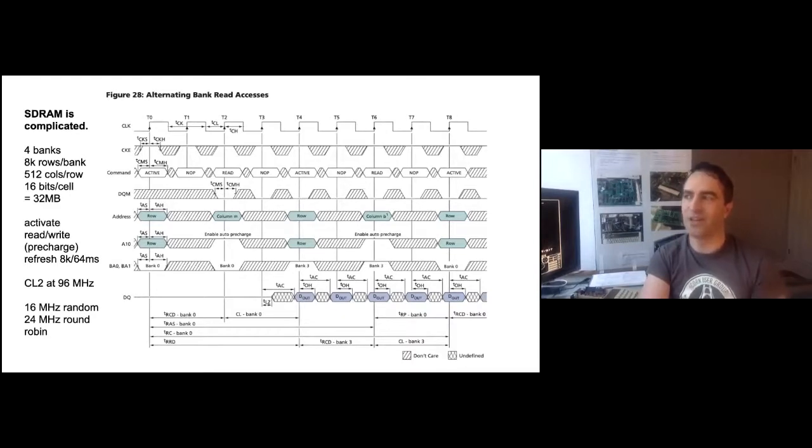The worst bug in this was that the SDRAM is 16 bits wide, but I only need 8 bits of that. Trying to be efficient, I used the low bit of the address to select the upper half or the lower half. I was writing everything correctly using the upper and lower bank strobes, but when I was reading, I would always use D0 to 7, and so every other byte would be incorrect. So the Electron would start up and say Acorn Electron 160K, and then I would use SR load to load something in and it would crash immediately.